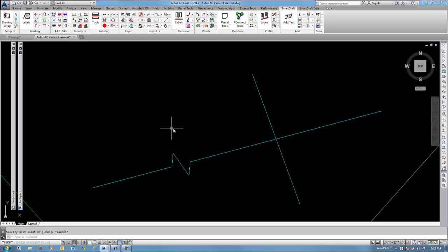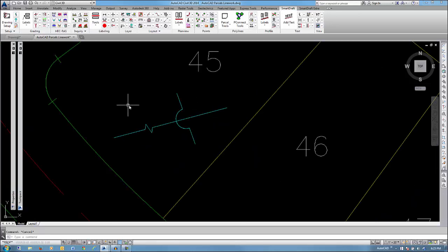If you were doing some irrigation type work and you wanted to show that these two pipes don't actually go into a T, but they cross without touching each other, you could add the crossing symbol. And again, it's not actually breaking that line, it's just adding the symbology to show that that one pipe does not tee into the other pipe, it just goes around it. So more or less just a drafting symbology.